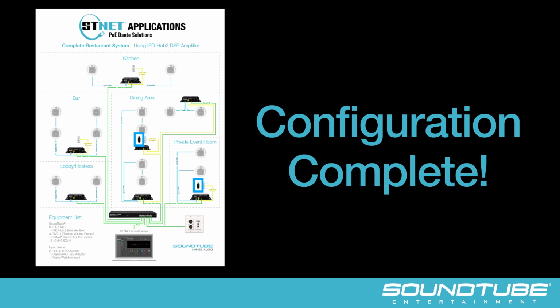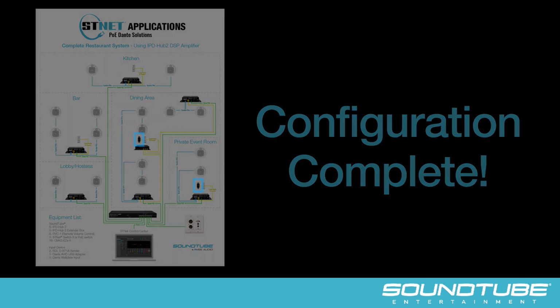This can be done by adjusting the toggle switch on the RVC to its B position, which will activate the preset that we chose under the preset select. We chose preset 1, which will switch it from our remote source Dante audio or whole house music to our local input, which will be the Bluetooth input device.